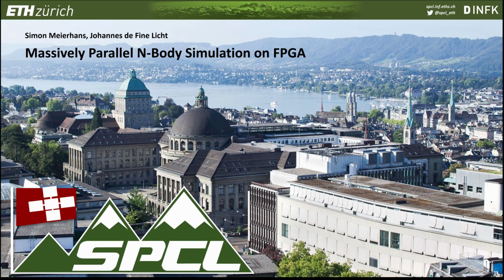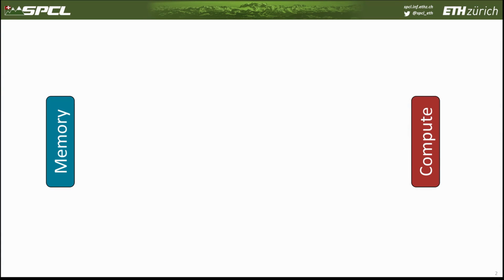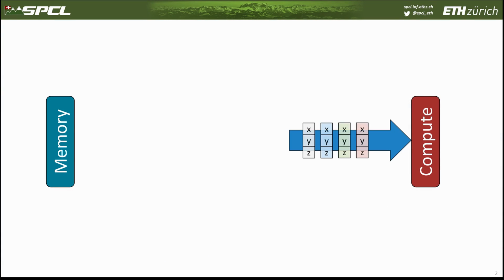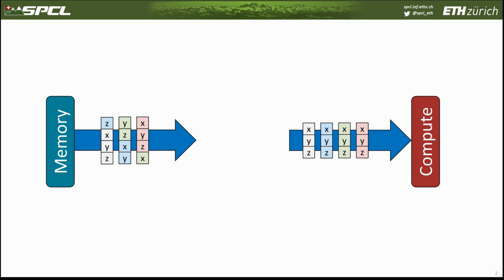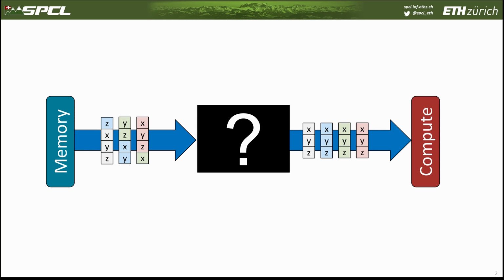This submission presents a high-performance n-body simulation accelerator, and this video will focus on key modifications to the build flow that were necessary for this project. We were faced with the issue that our compute kernel required reading 3 vectors in a pipeline fashion representing the x, y, and z dimensions for the simulation, whereas the AXI master interface only allows data widths that are a power of 2. Implementing this highly irregular conversion turned out to not be feasible in HLS, so we had to use a Vivado IP instead.